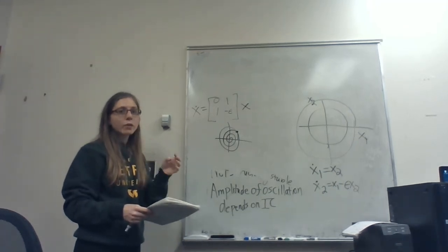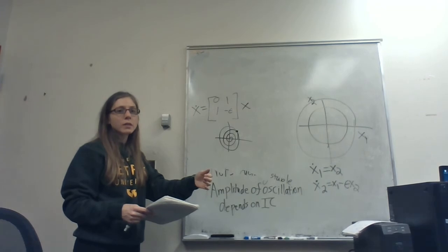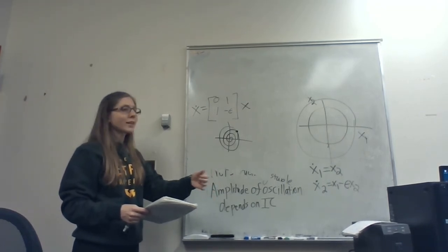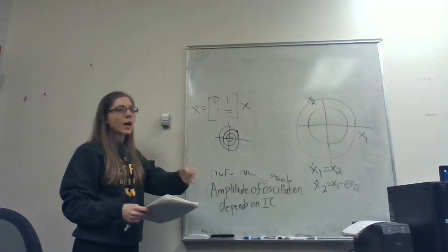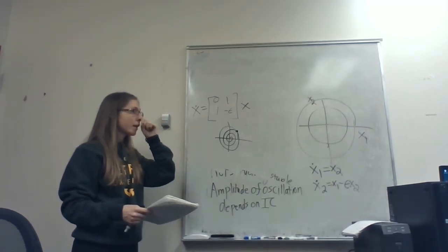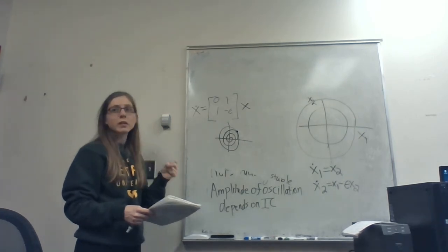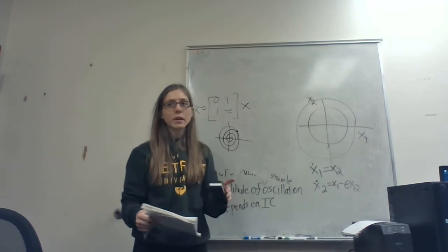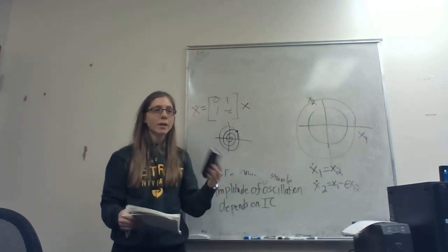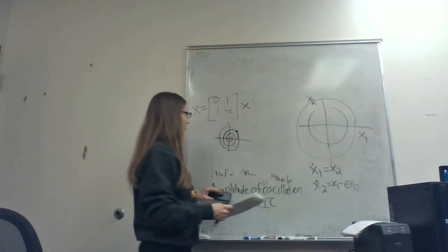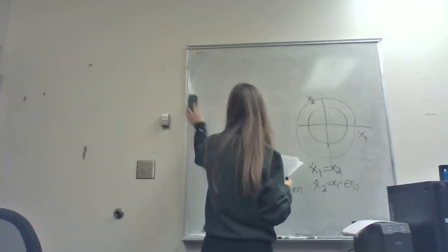So the likelihood that you're going to have any real system that really has these eigenvalues on the imaginary axis, and the full system is 100% modeled by that so that you have no disturbance, is so small that you'll probably never see a linear system really in a periodic orbit. Okay. So if you want to see any system in a periodic orbit, it probably has to be a nonlinear system, because those have structurally stable periodic orbits that can be achieved for certain systems.